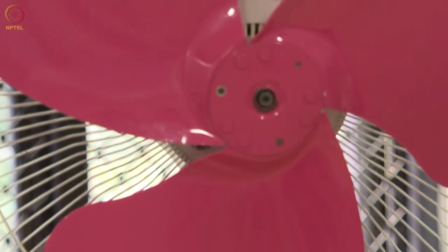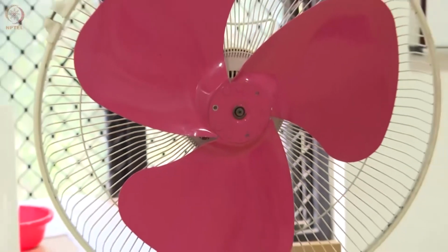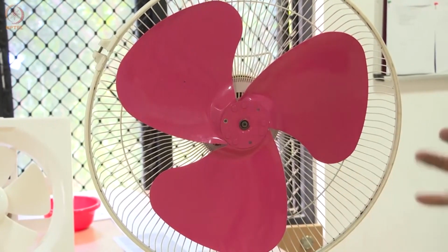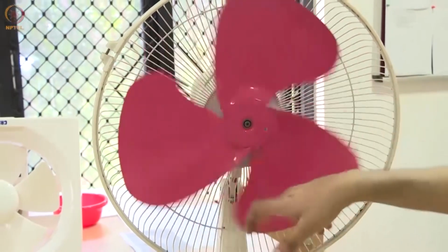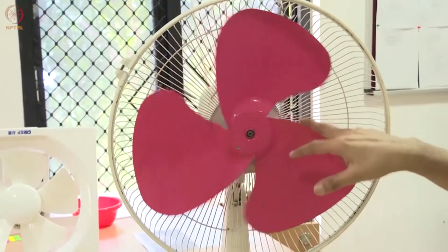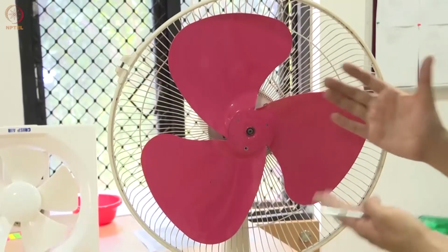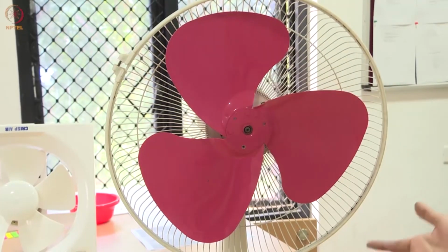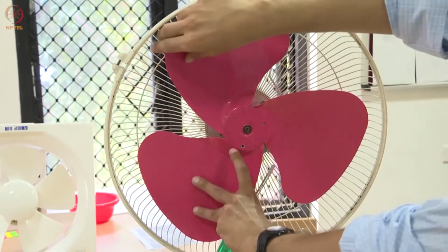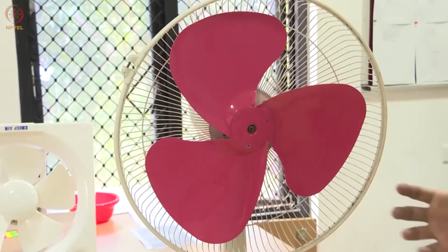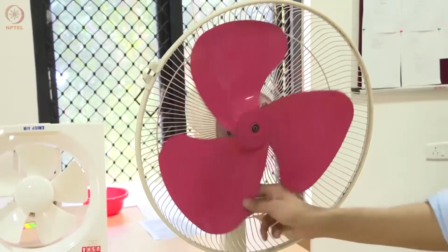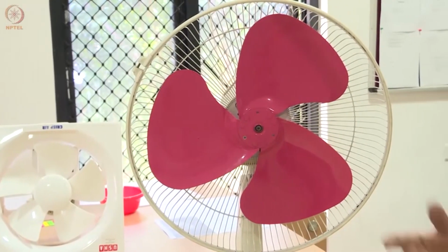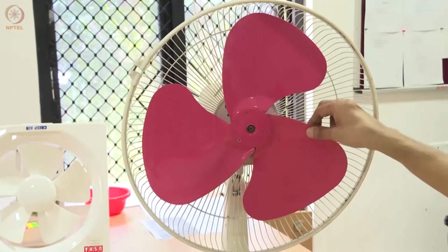The operating speed of the fan will typically be somewhere around 1500 RPM. If you take slip, it is roughly around 1450 when it is running at full speed. Which means the fan itself has to be dynamically balanced. Otherwise, if there is any residual imbalance in either the motor or the fan blade, the fan will start to vibrate. That's why if any of the blades get bent out of shape, you will find the fan vibrates quite vigorously. Newer fans, the next model that I show, have an injection molded fan blade, contrary to the fan blade that you see here.